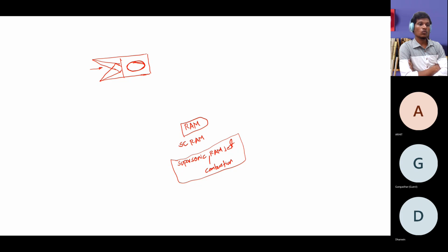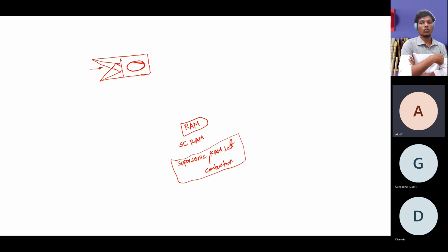That's a nice question. So far, doublets are not seen in any theoretical or experimental practical situation that I have seen, but doublets are mostly used with the idea of creating walls on the surface, or for modeling as singular points in theoretical aerodynamics. Suppose in the panel method, you use vortex for modeling the flow over an aerofoil on the surface. In the same way, the vortex lattice method also uses it.